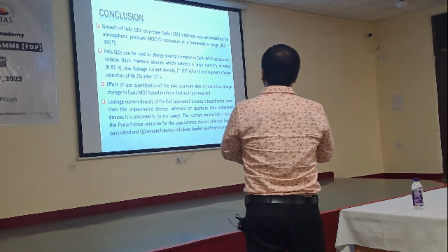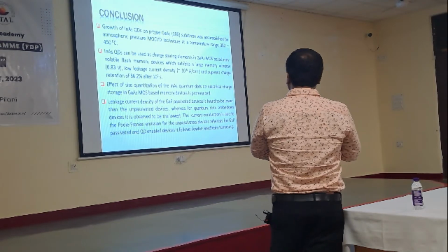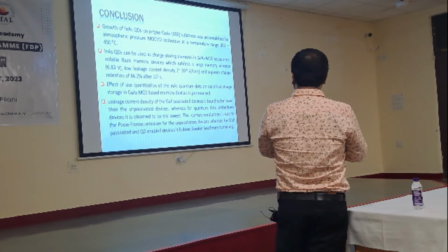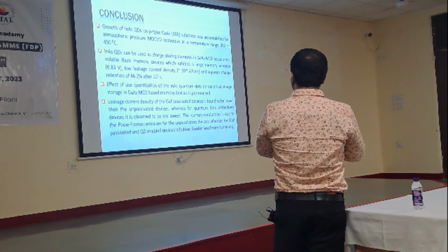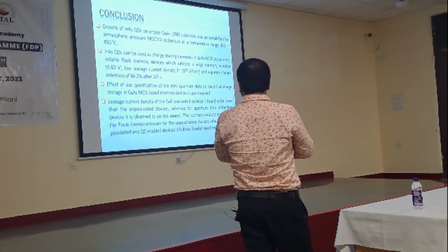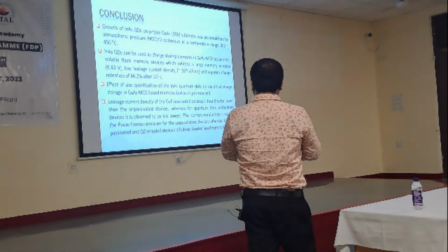I have also studied the size effect as well as the leakage current density and the quantum sum model, where in the case of passivated devices it follows Poole-Frenkel, and where quantum dots are present it follows the Fowler-Nordheim tunneling mechanism.